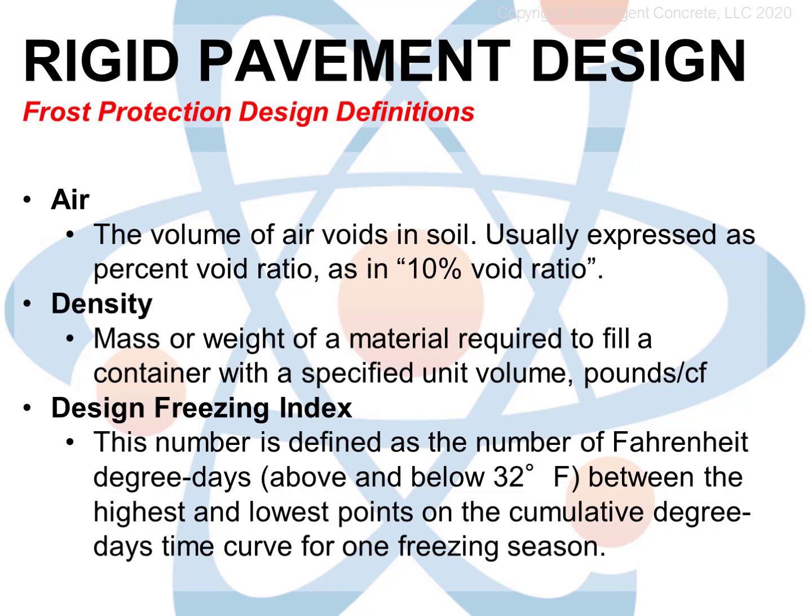If there's a lot of water and it freezes solid, it's going to expand, and as it does, it will lift and potentially damage any surface or structure supported by it. What we're going to try to achieve by compaction is to increase the density of the soil and decrease the void ratio, thereby leaving much less space for water to occupy. We also gain the structural advantage of having a denser, stronger material, because dense materials simply cannot be compressed as easily as less dense materials.